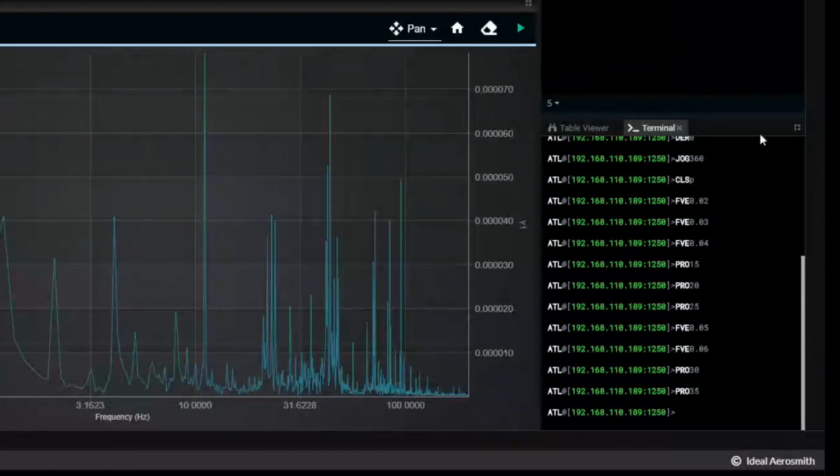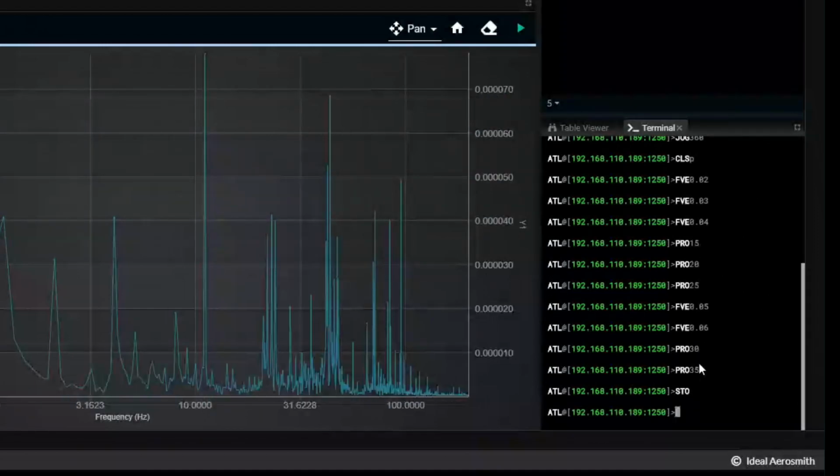If all you need the system tuned for is rates, then we are done tuning. And let's not forget to save the package so we can keep this tuning. So let us stop it and turn the servo off. And we will call our package FFT rates. So we will save it with the PKS command and we'll do FFT rates. And so if we list our packages, there's our new package, FFT rates.